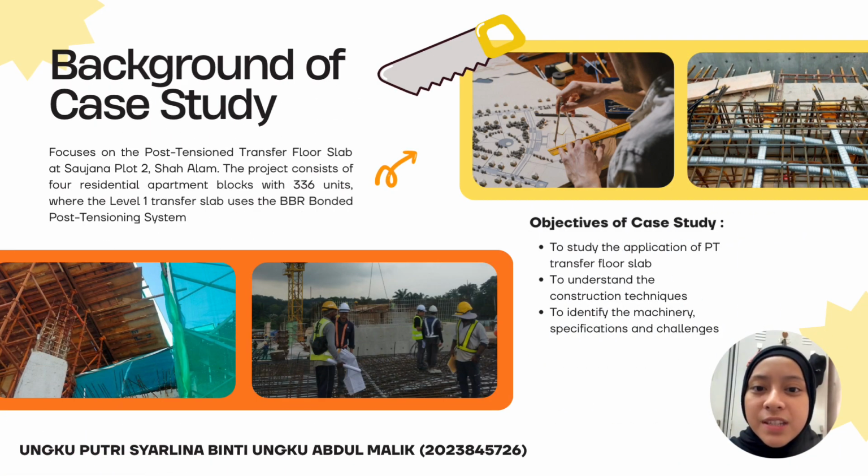Next, for the background of the case study, this case study is based on my internship project at Sarjana Plot in Shah Alam, Selangor. During my internship at BBR Construction Shah Alam, I had the opportunity to learn new knowledge about the construction of the post-tension transfer floor slab used in this project. The development consists of 4 residential apartment blocks with a total of 336 residential units. The transfer floor slab at level 9 uses the BBR bonded post-tensioning system to improve the structural efficiency and create larger open spaces.